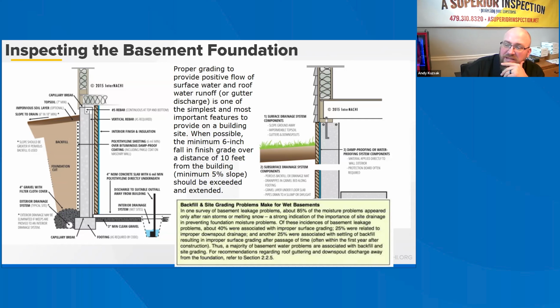Inspectors often find shrinkage cracks in poured concrete foundation walls, which may allow water penetration. Utility penetrations through foundation walls should be carefully sealed on the exterior face prior to waterproofing and backfilling. High-quality urethane caulks are most suitable for this application, and the wall construction should be inspected for penetrations due to voids or other problem areas and appropriately repaired and sealed.